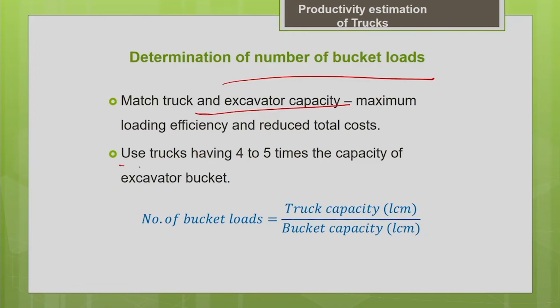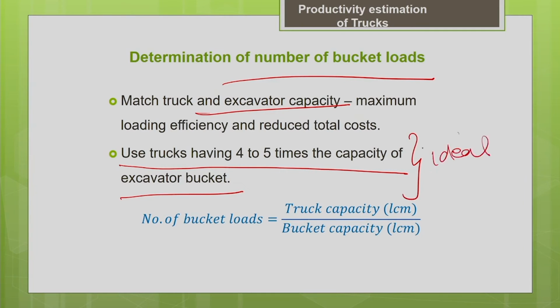Okay, use trucks having 4 to 5 times the capacity of the excavator bucket. So this is the ideal case. This will give you the maximum productivity. So match the truck and the excavator capacity.